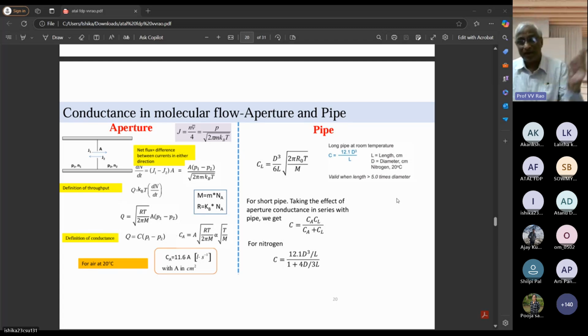That's why molecular flow conductance plays a very important role. Just like the rotary pump, we have seen 120 liters has gone to 1 liter. Similarly here, for a turbomolecular pump, you purchase a 40 lakh pump, it is around 1000 liters per second. You connected it, and by mistake, you made a small pipe, very small in aperture diameter and long in length. Then that 1000 liters per second has gone to 1 liter per second. Then where are you? So the company fellows have sold and gone.